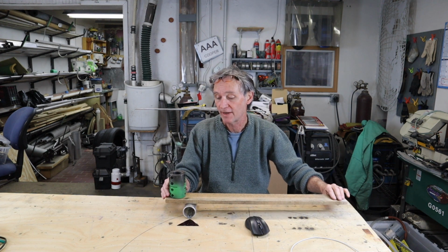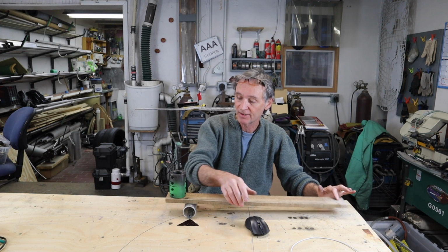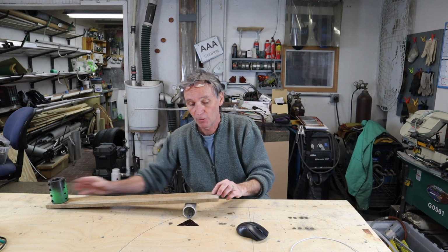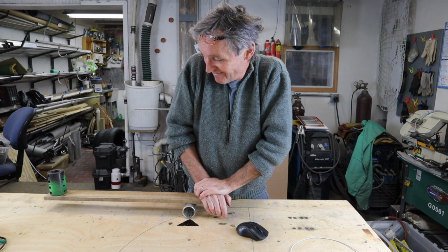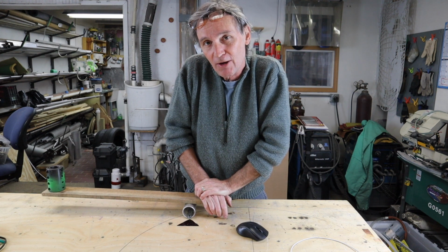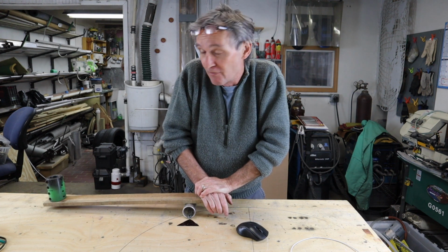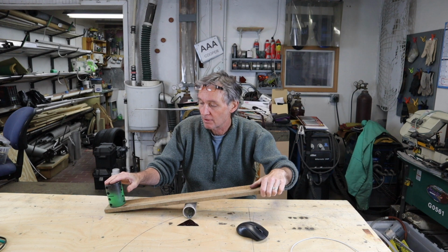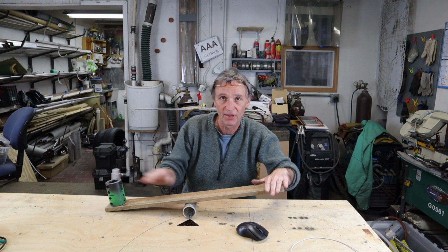So right now, with the weight very close to the fulcrum, I can balance this probably 5 pounds of steel with the weight of a cordless mouse, which is probably 3 ounces. But if we go all the way to the other end, if I want to lift that now, I'm going to have to put in 20 or 30 pounds of force to get that off the ground. So very useful. It's also very useful because the motion of the load is opposite to the motion of the force. So we have gravity. If you want to jump on this end, gravity will help you, and quite often we want to lift things. So it's all round first class lever.